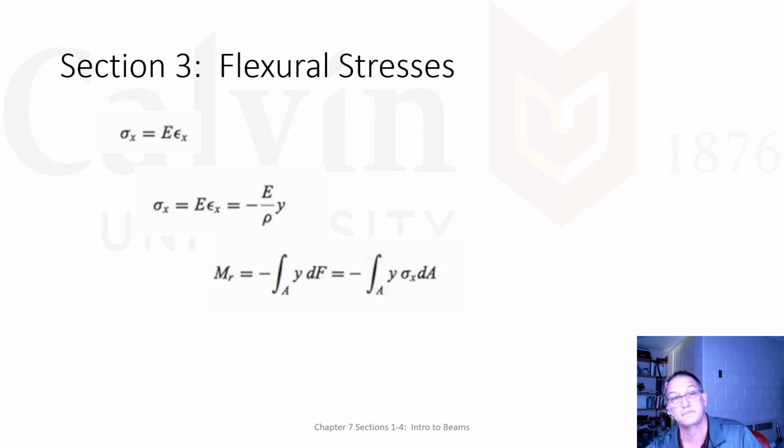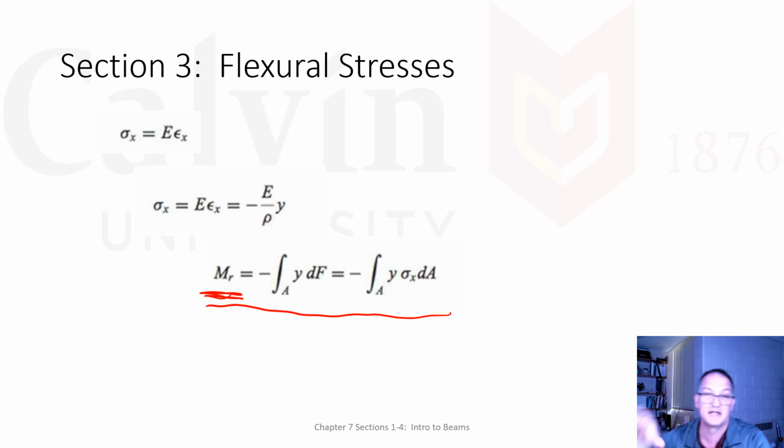But one more. I can look at the moments across any face, the sum of the moment acting on that face, by integrating the moments, such as y dF. That's the torque. I'm integrating the torque there. Well, that dF is equal to stress times dA. And I have the stress in the x direction as a function of y. So this is all making sense.